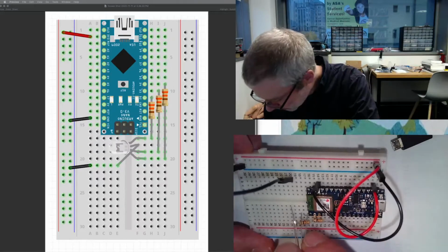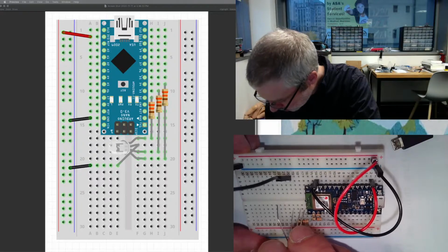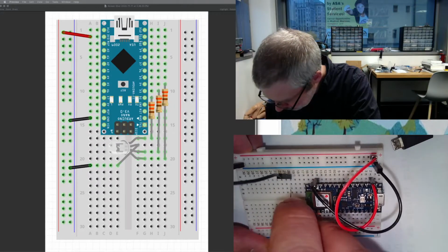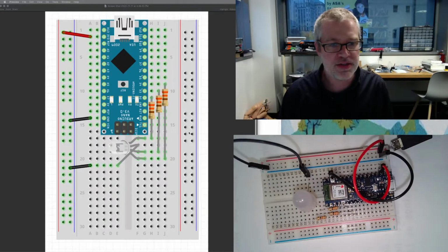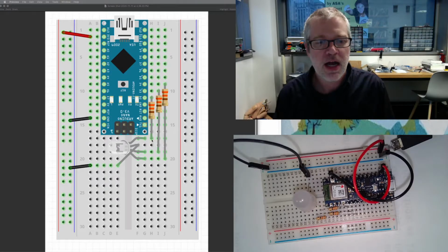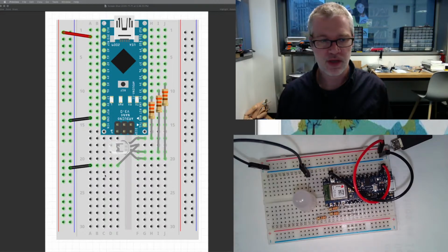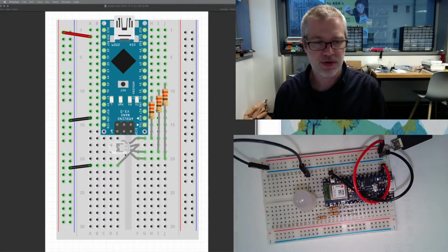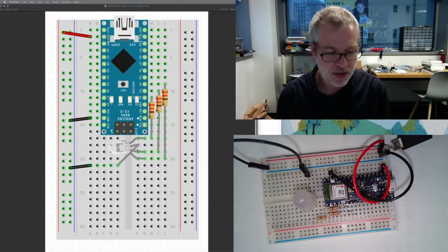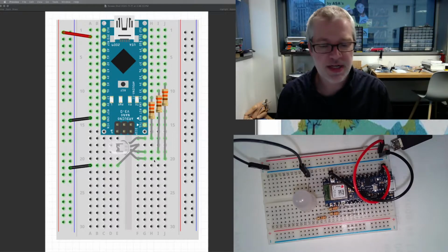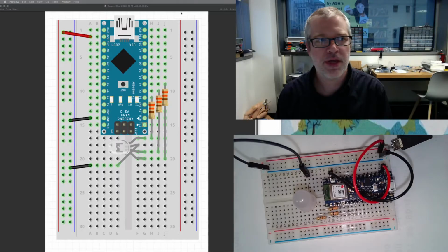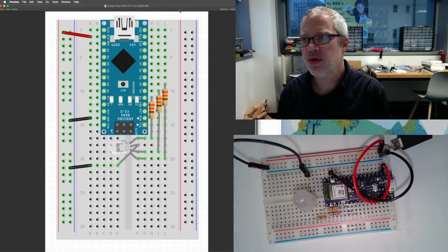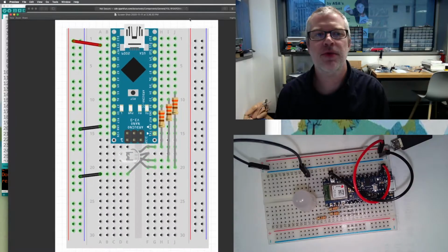So I'm going to plug this back in here, and then I'm going to talk real briefly. Pop. Just goes in like that. You can see also in the illustration here how that's set up, right? Fritzing doesn't really have a perfect way of doing this, so that's why it looks a little bit awkward. But the pins here, each one of these legs corresponds to a red, green, or blue element, and I know how they look because I checked out the data sheet for this.